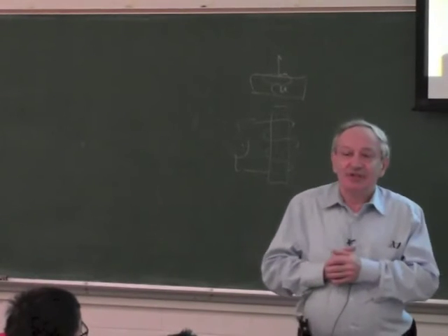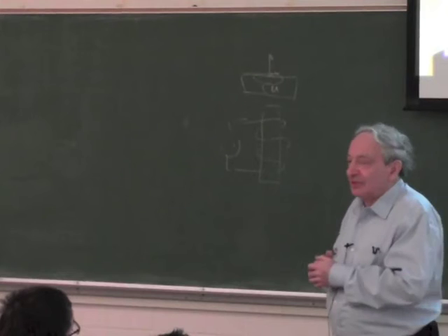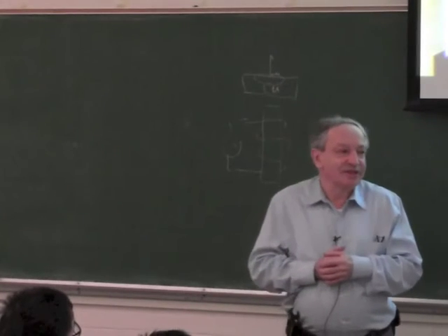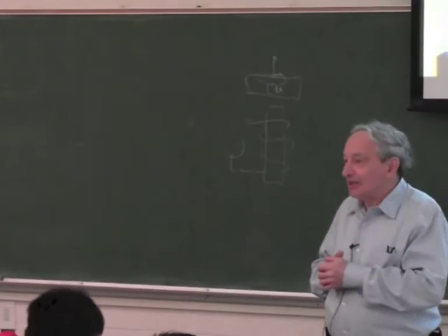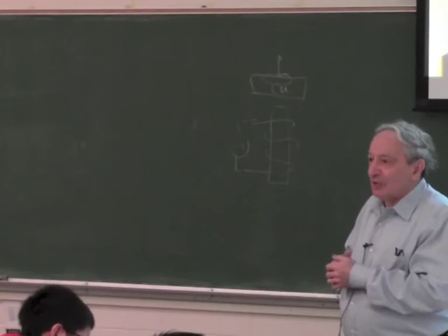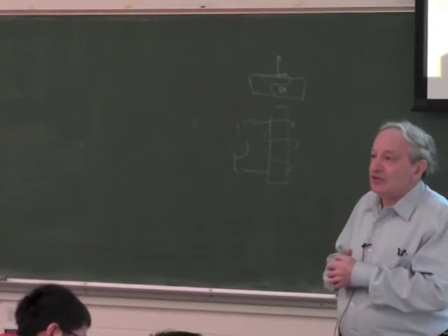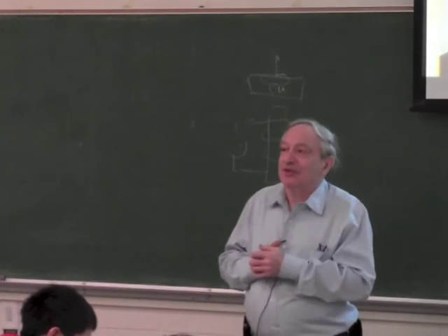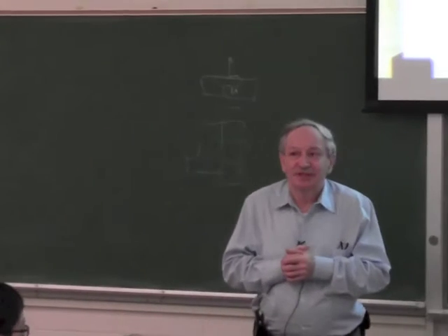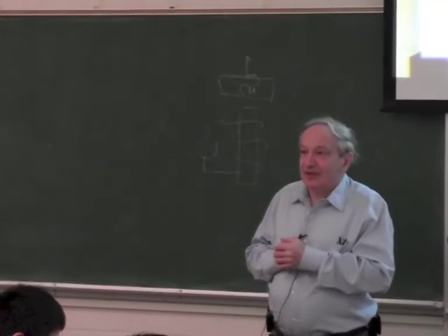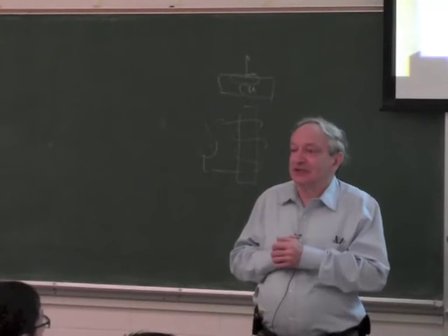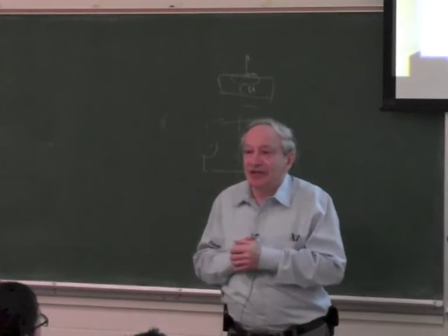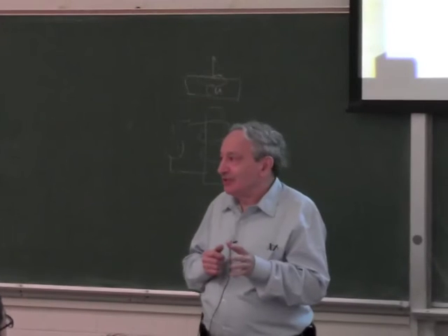Okay? Now, steel is not a very good conductor compared to copper and aluminum. So steel is a very good ferromagnetic material, and a poor conductor compared to other metals. Because of that, the attraction of the magnetic field overpowers Lenz's law by a lot. Now, if you could find a material which is very conducting and a little bit magnetic, you can find a material which should be balanced. The force will be zero.